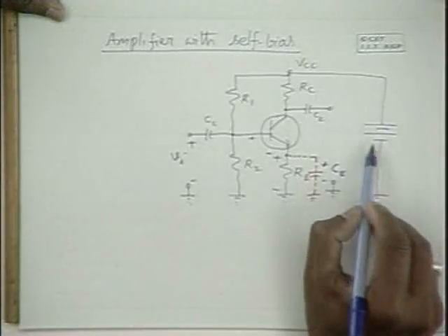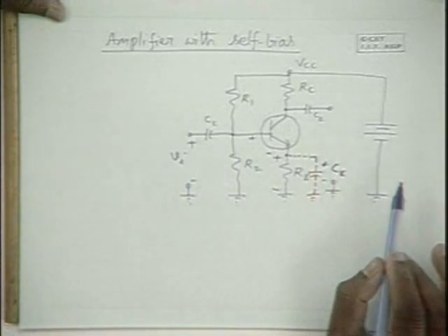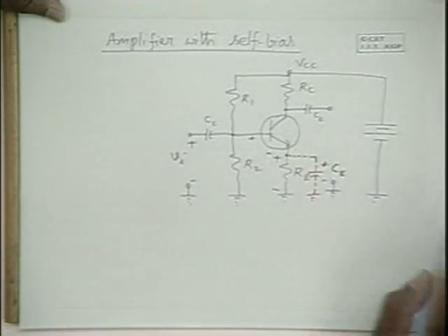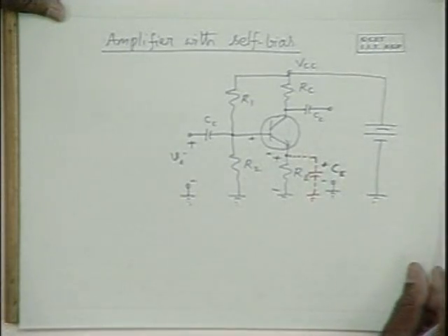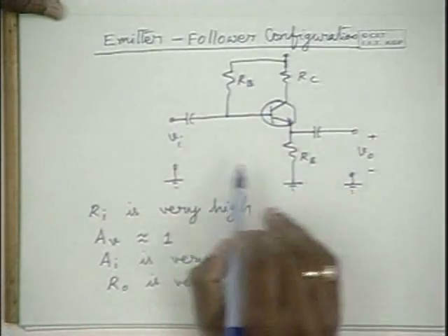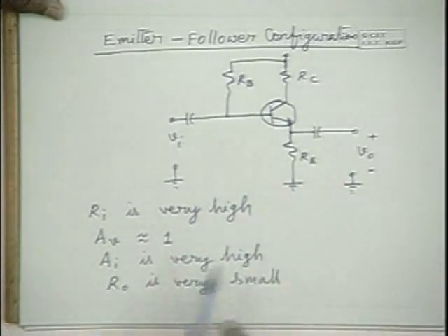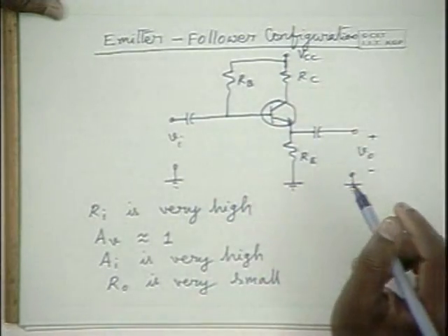If you use this kind of a circuit there, it doesn't work. So in such cases, what we do is we include an emitter follower here, see that its output impedance is low, and then connect a low impedance load to it. So an emitter follower circuit is used for this kind of applications, matching purposes.